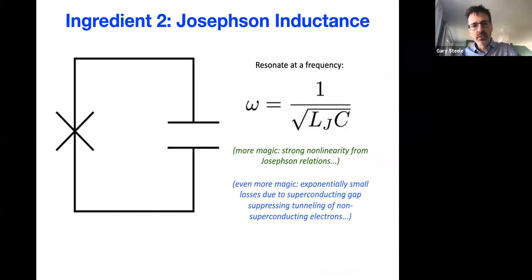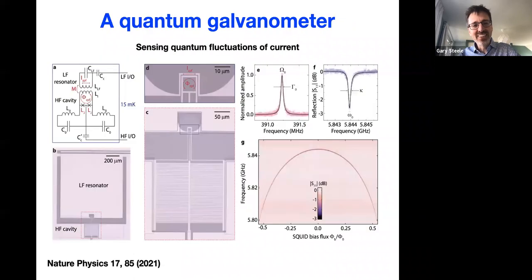This one over here, these ones here, we had to develop a new type of junction technology. Because we wanted a lower anharmonicity, we wanted less nonlinearity. That involved about a year of testing junctions in the clean room. I think my PhD student Ines made about 100 samples. But once you have the recipe working and you have the in-house knowledge, then turning a sample around after that is like a week or so.